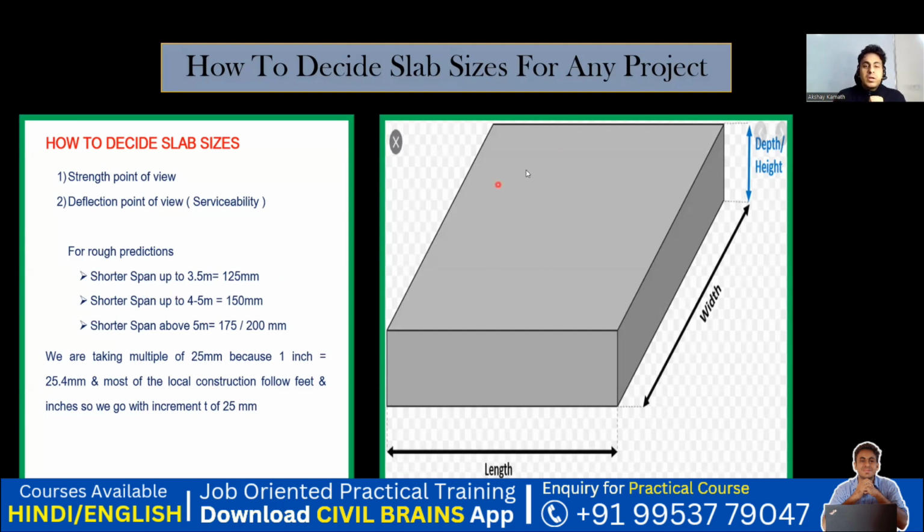Okay. So let us consider this is my slab. This is the breadth of my slab and this is the length of my slab. Or I can say this is my shorter span and this is my longer span. So if your shorter span is up to 3.5 meter, that means if this distance of mine is up to 3.5 meter, the slab thickness I can take is 125 mm. It doesn't matter what the long span is, only the shorter span we are concerned with.